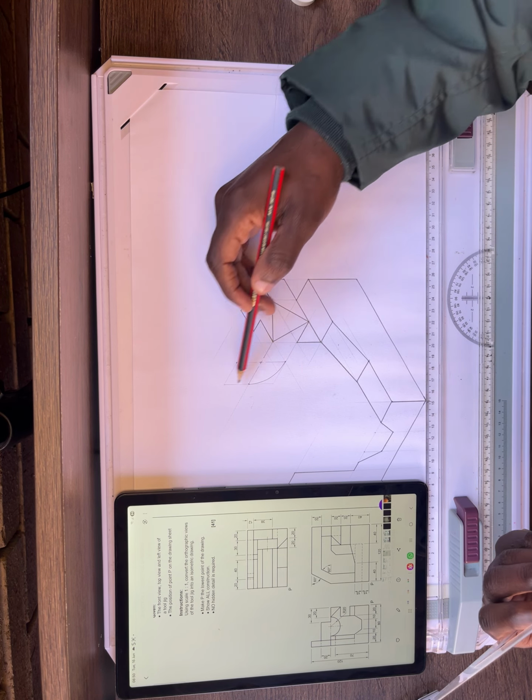There it is. Then now you have got your what? Your half a circle there. Remember, this half a circle, we are given this detail line, which tells us that is a half a circle here, and also going backward, it's a half a circle. Therefore, we have to take these points and project them at the back here.